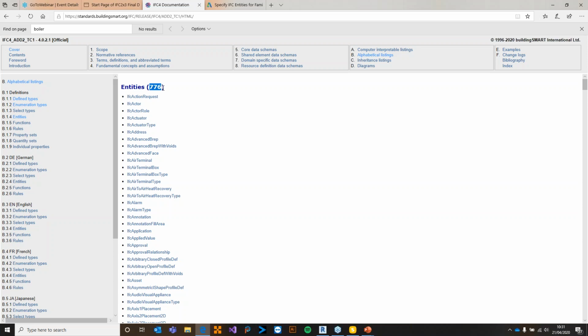So if you set your Revit up to work with 4, but then you need to export 2x3 for a project, it's not going to give you the desired results. So typically you just want two setups. The process is identical for what you do in Revit. So you define the type and the class, the type and the subcategory to be more specific. But you need to have two setups, one for 2x3 and one for 4. Hopefully that answered that question.